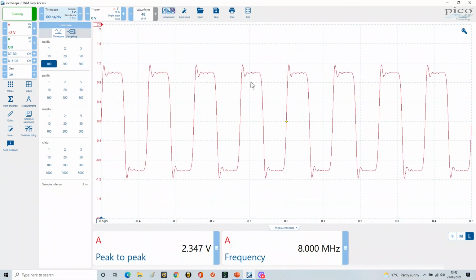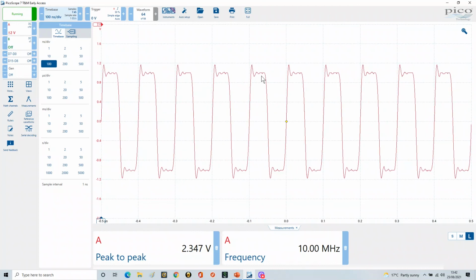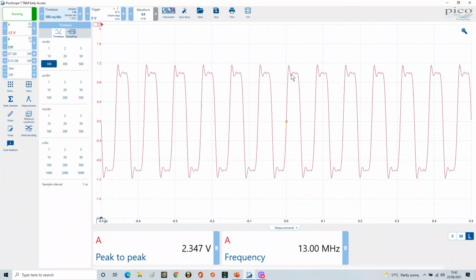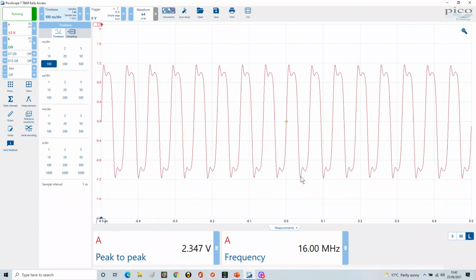And you're starting to see this ringing as well, but also you'll start to see the formulation of these double peaks. And this is partially to do with the fact that we're getting the close harmonics. This is 16 megs. So if we times that by 3, then the next harmonic is 48. So 48 megahertz is the first odd harmonic. And so there's our fundamental at 16 megahertz. So part of this frequency in here will be sitting at 48 megahertz.